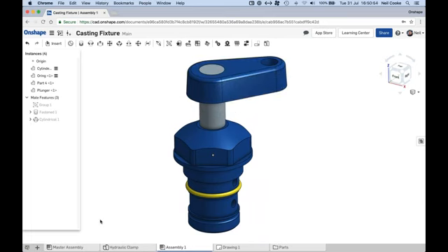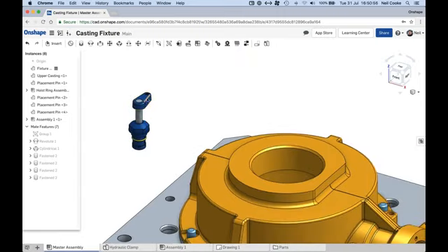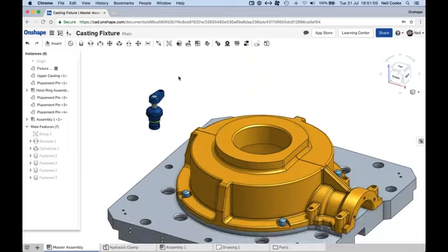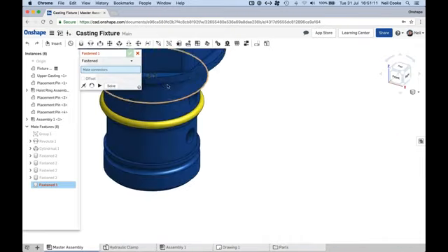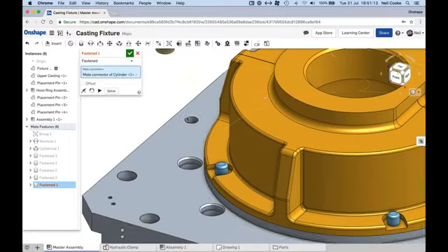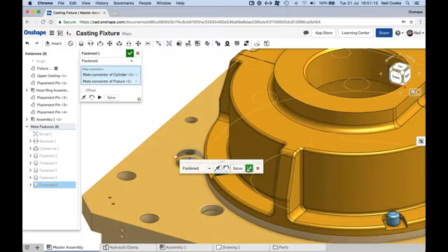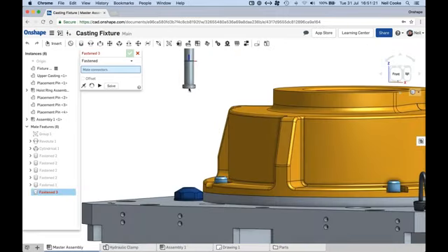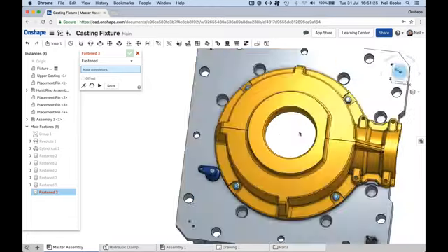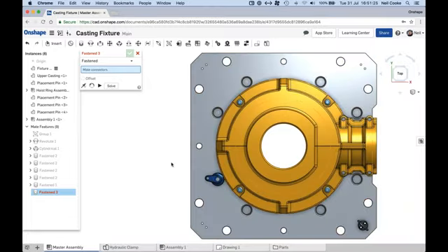Okay, and then as we go back to that master assembly, you'll see, of course, that it is updated. There is no such thing as a flexible assembly in Onshape. Basically, everything is flexible. So it just means that you can have this assembly here, for example, and we'll mate that to here, for example. And now because I didn't put any limits on that, you can see that things come out. But let me just pull it down to approximately there and spin it up to the top.